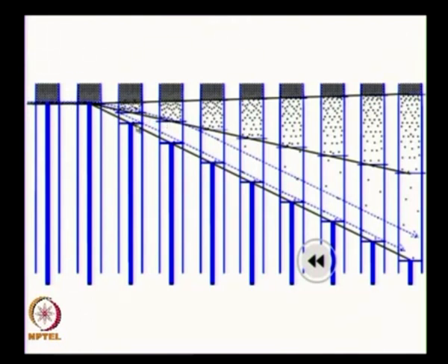We saw that a similar thing is happening in compression wave, the oblique shock also, but I cannot show you what is happening inside a shock. Here it is a big region, I can show it to you very nicely. In the other case, the area between the streamlines will be very large before the oblique shock, and if the streamlines turn, they will be much closer to each other after it. I cannot show you anything more than that. In here I can show that the stream tube is expanding during the expansion fan, after that it is staying constant cross section between them.